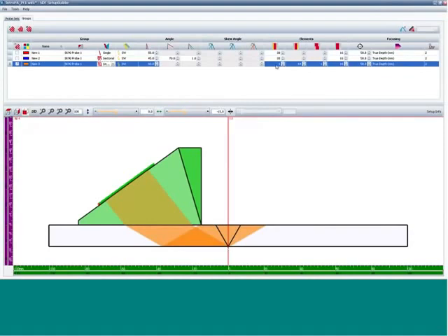This is defined as the element start position, element 1, for the first A-scan. I want to use the entire probe, so I will stop at the last element. Okay, I might not need all of that coverage, but I have the ability to use it up until the last 16 elements.